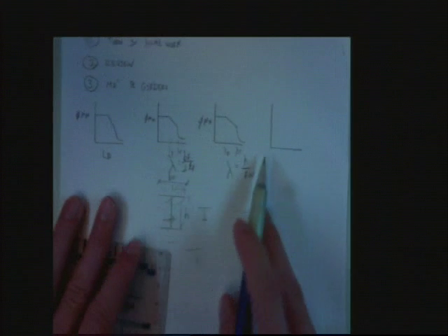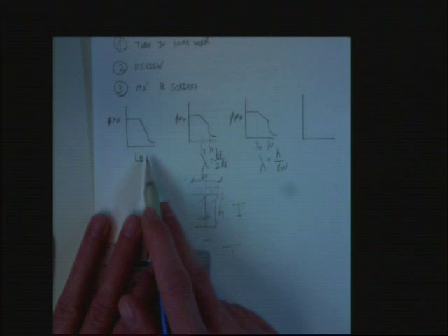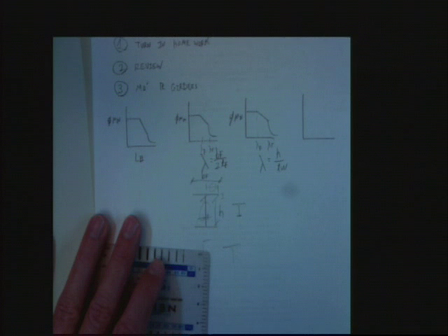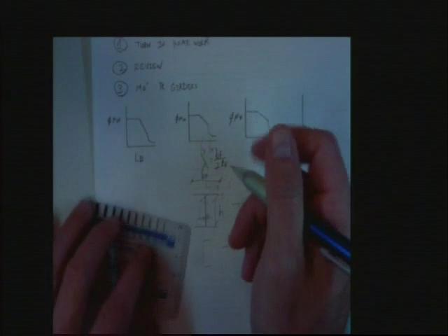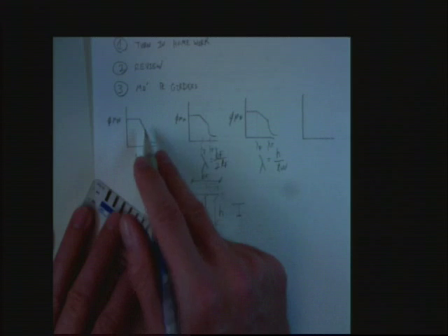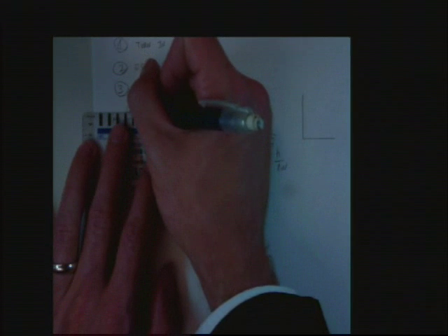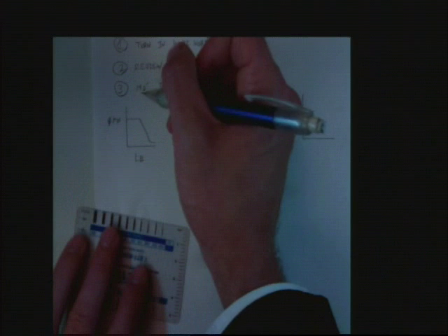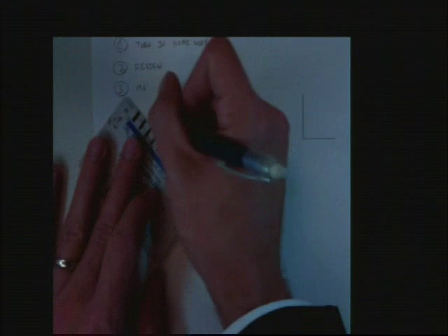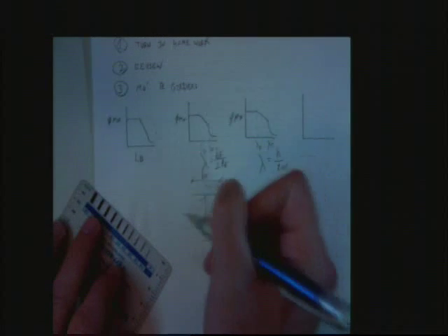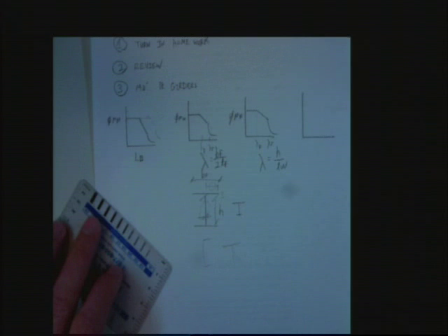Hey, before we go on to our fourth Snail Chart of Apocalypse, we got to this one. What is the C sub B factor? What does it do? Increases capacity. There you go. Increases capacity all the way around, right? No. Where does it increase capacity? Only for lateral torsional buckling. So our C sub B comes somewhere out here, and it's capped. Remember that? We're going to come back to that in a second.